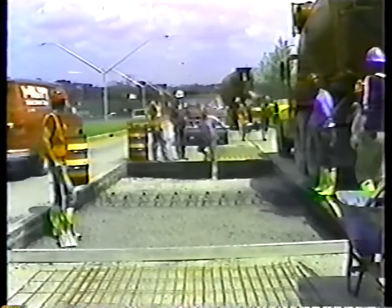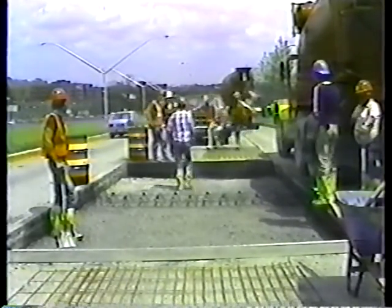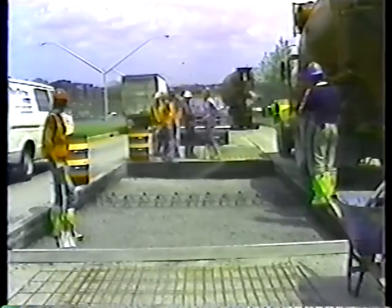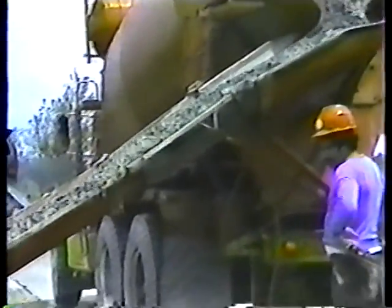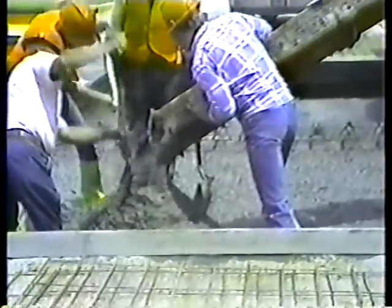Okay, before any concrete is delivered to the work site, make sure you're ready for it. For example, if you're patching, is the base well compacted? Stable? Are the forms and reinforcing bars in place? If the job is really well coordinated, the concrete will be placed as soon as the truck arrives. So check the job site